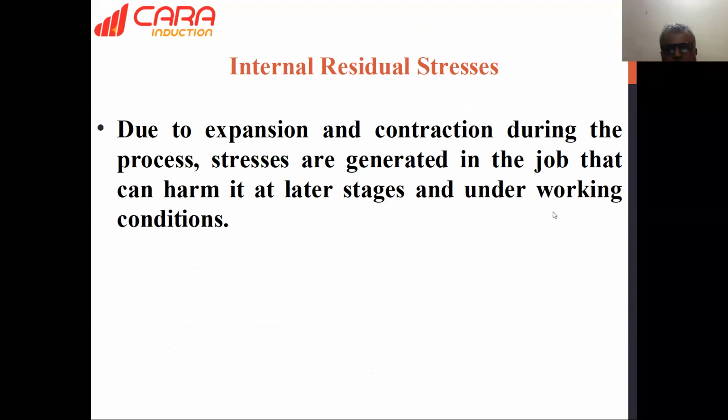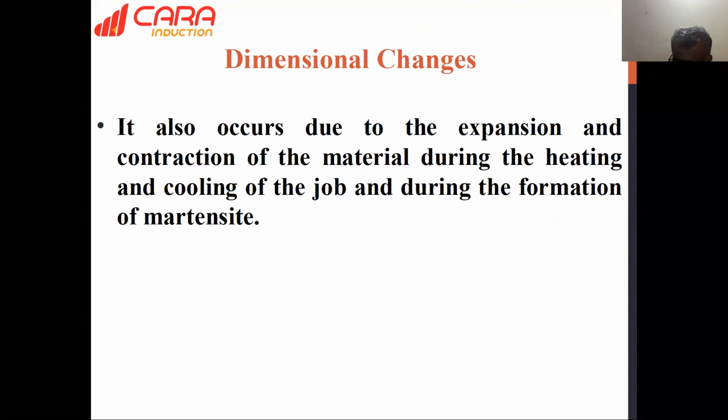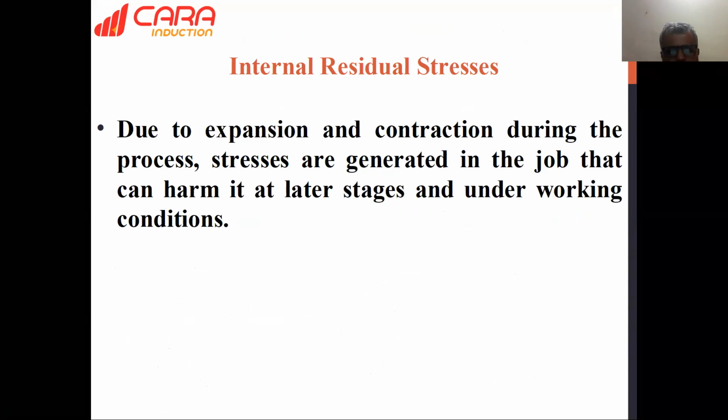Again, internal residual stresses. This is the main problem we are facing, and we are not getting the exact solution for the particular reason. We need to take a lot of data and study it. In your question and answer session I will give much more information about internal residual stresses. This is mainly after induction hardening, in the grinding and turning operations, where this problem gives us trouble. It may be in the camshaft after camshaft grinding, or crankshaft grinding, or any other critical part. Next.